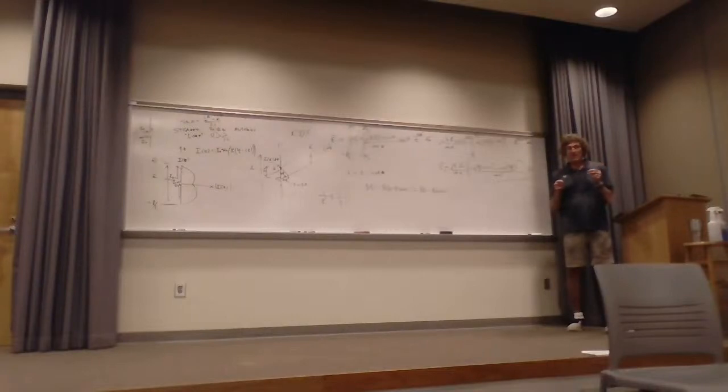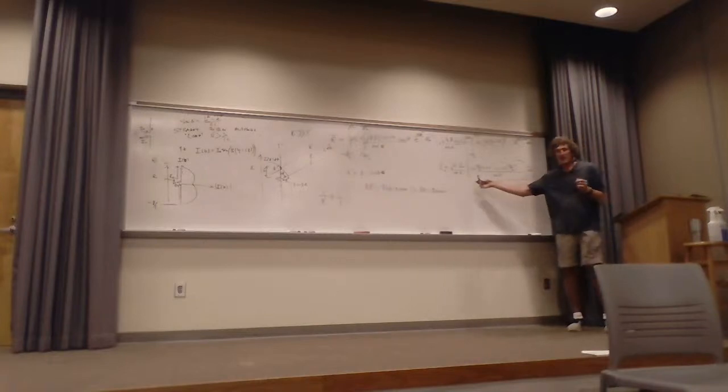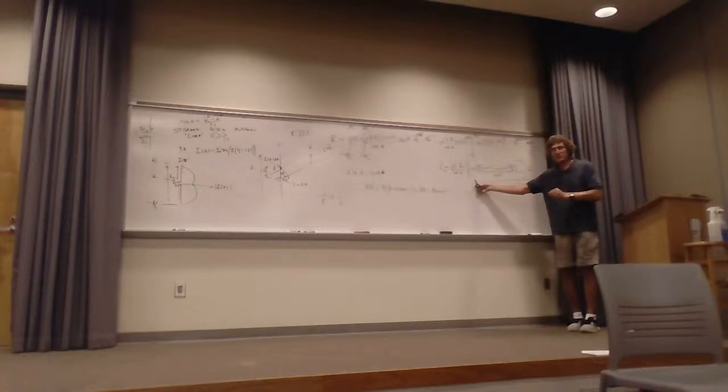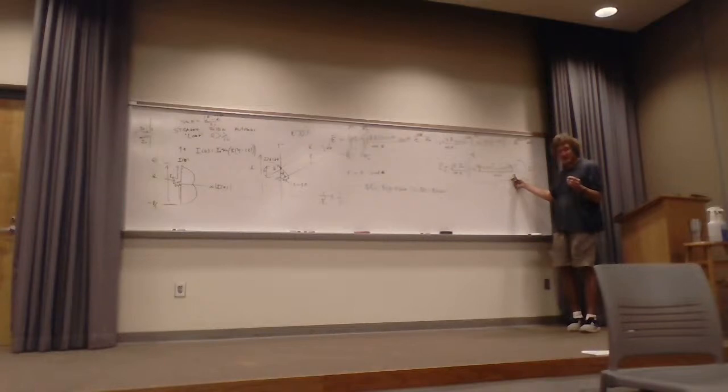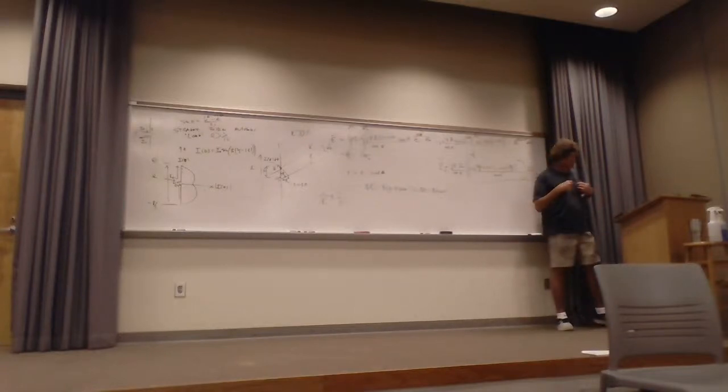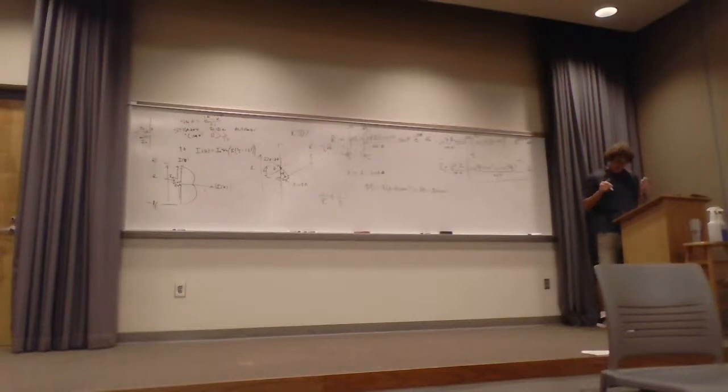So now, in order to get the directivity, you have to find the normalized power density, and I'm going to try to make this clear to you. Anytime you have an E field or an H field that has an angular function like this, the power density will be proportional to that angular function squared, always. Y'all with me? Because power density is 1/2 magnitude of E squared over eta. If you wanted to use H, it would be 1/2 eta magnitude of H squared. It's always proportional to this angle squared. Got me? Period.